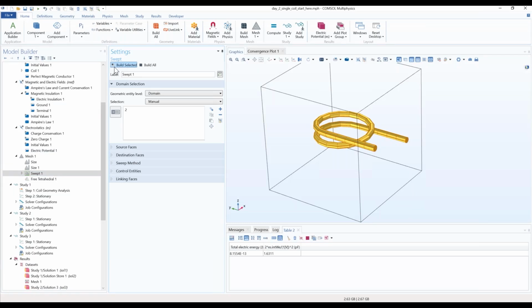You will always want to perform a mesh refinement study, refining these meshes, trying out different meshes, and seeing how the solution changes with respect to mesh refinement. These techniques happen to work well in the geometric cases that we're looking at here. They're not necessarily appropriate in all cases, but they do work well for what we're looking at here.